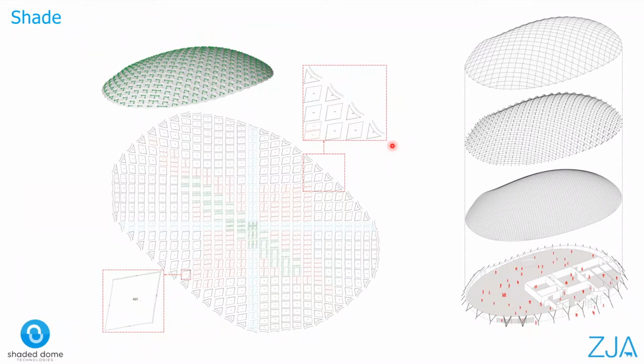Orientation of the patches on the roll was equally important. This is due to the warp and the weft, which influence flexibility within the fabric material. For our audience who doesn't know what warp or weft are, they are the basic components used in weaving to turn a thread or a yarn into fabric. So the forces on each of these patches are actually running in both directions, but they are not really perfectly orthogonal. So we had to rotate each and every patch until the deviation in both directions is the same.